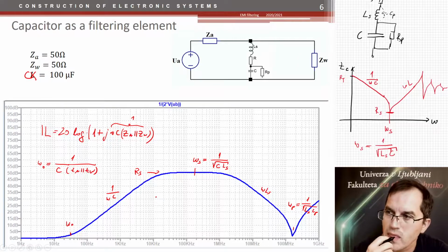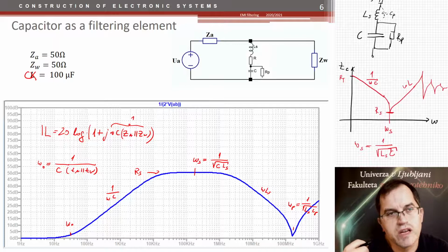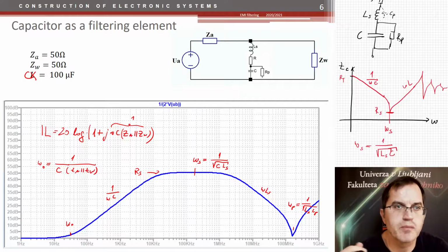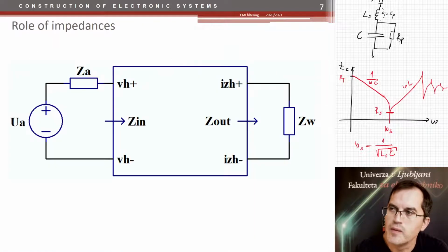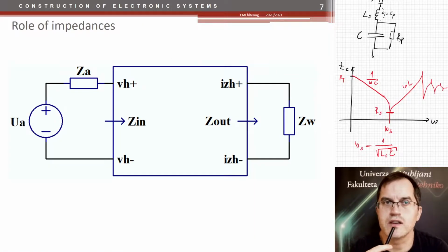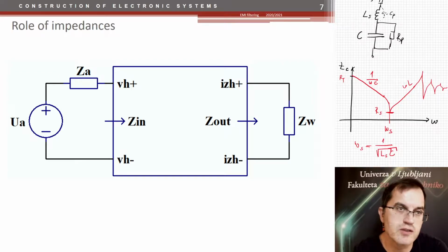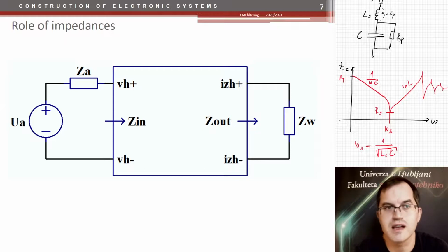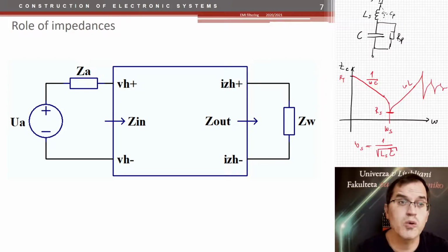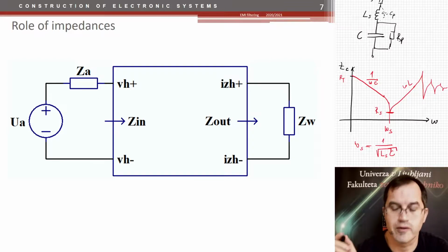What else? Well, we've shown that inductor and capacitor are both good for filtering, but they are limited by their non-ideality parameters. Now, what about the choice, which one to use? Because both are actually good. But the thing is, first of all, they are different regarding their idealities and prices and sizes, but they are also very different in terms of the impedances, which might be a little bit awkward, but let me show you an example of that.